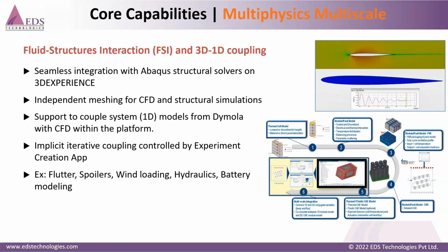And coming to the multiphysics or multi-scale capabilities, which is specifically the fluid structure interaction as well as the 1D plus 3D coupling. We have seamless integration with Abaqus structural solvers on the 3DEXPERIENCE platform itself. So we do have roles which are basically the Abaqus structural, which comes with Abaqus structural solving capability. And when it comes to the meshing, here in the CFD role itself, we have independent meshing for CFD as well as independent meshing for the structural simulations.